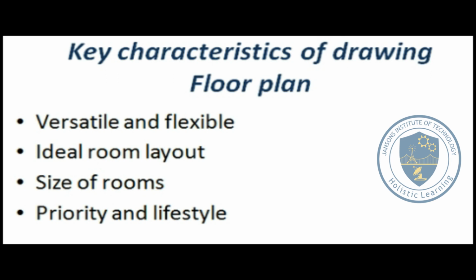Second one, room layout. We have to make sure that the bedrooms are far away from entertaining spaces. The bathrooms should not face common entertainment spaces like the dining room or living rooms. Most people will like it if the kitchen opens to the dining or living rooms, so whoever is cooking can still interact with guests or keep an eye on the kids playing.